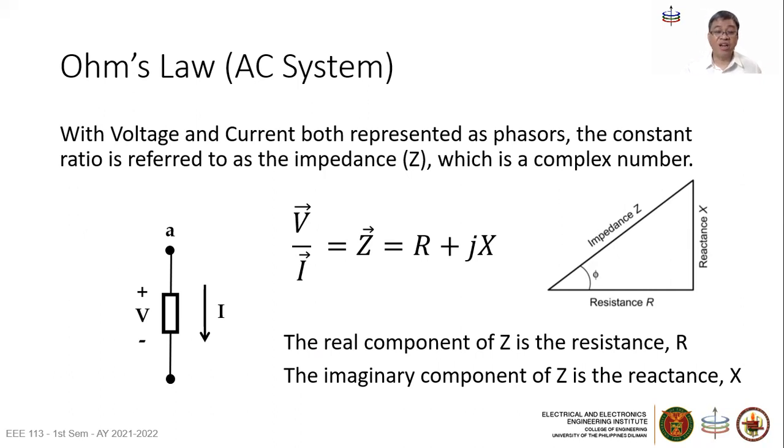So from here on, we now look at these ratios, V over I, which is equal to the impedance. Of course, if these are both DC signals, then you have R only here. This one drops to 0. If you have an AC signal, then these three components are available. So we can write this as a magnitude Z there and an angle phi there.